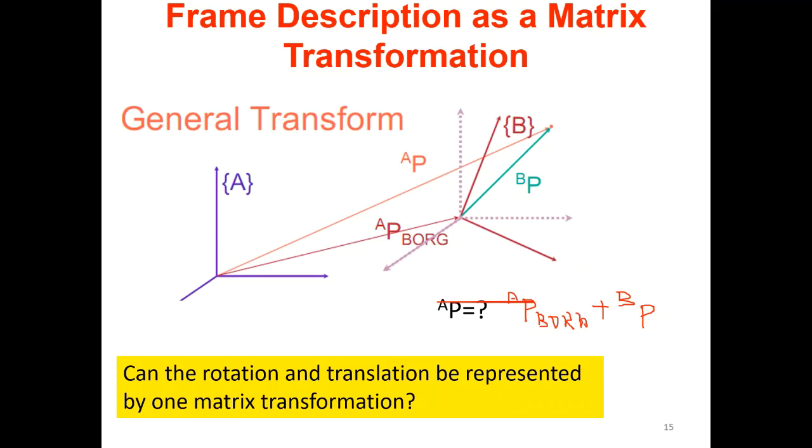It's only now you have multiple frames and different vectors belong to different coordinate frames. So you can't simply add them together because some of these coordinate frames are disoriented, right? You can't simply add them together because x and x are not aligned. So before you add two vectors in a multiple coordinate frame system, you got to transform all these vectors into one single frame. After that only you can add.